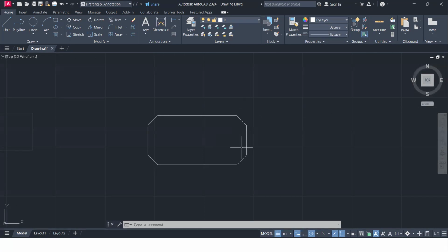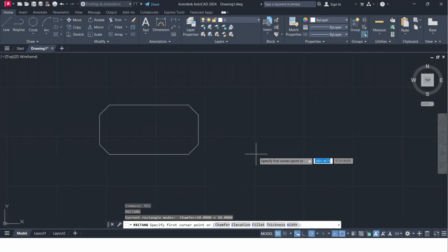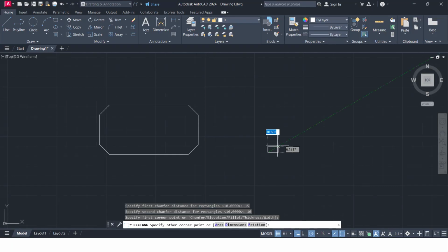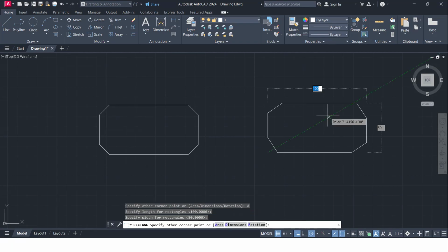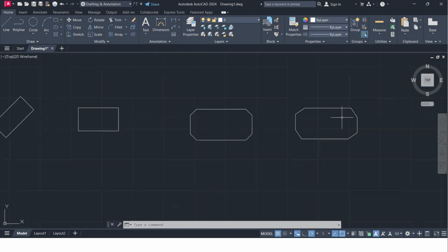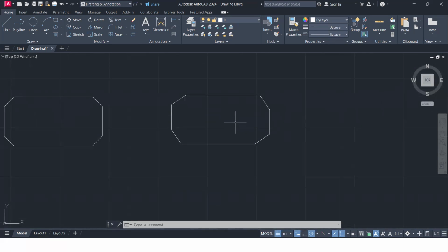If you need to draw the chamfers here with different distances, suppose here I want to make a chamfer. First of all, I make a chamfer of 15, and then the second chamfer I want to make is 10. Okay, then what we do? Just click on this part, and then here this will be a chamfer, right? Okay, one is your 10, and then the second one is your 15, right? Yes or no? Okay, you can also create this type of thing by use of the chamfer, where your cutting angle is changed right here.